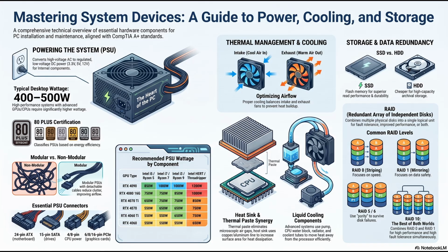The source lists 4 mandatory maintenance checks. First, meticulous leak testing. Right. A cracked acrylic tube or a slightly loose compression fitting will drip highly conductive fluid directly onto your $1,000 graphics card, destroying it instantly. Terrifying. Second on the list is cleaning the radiator, which makes sense. Dust clogs a radiator just like an air cooler.